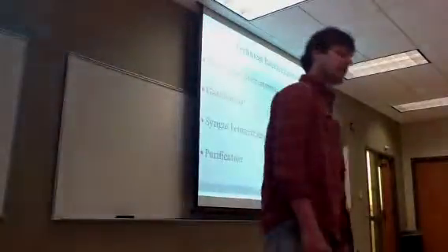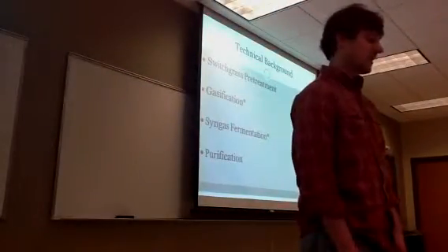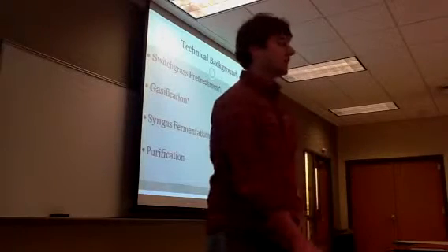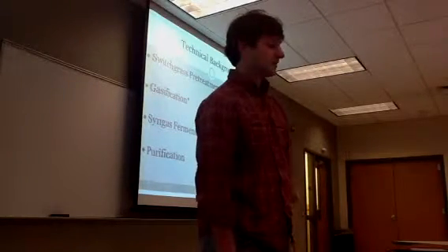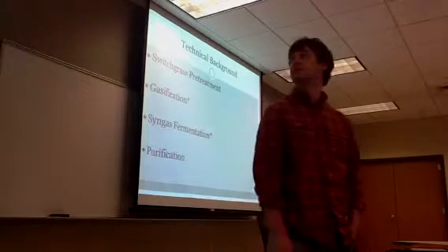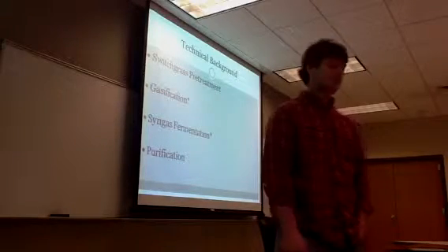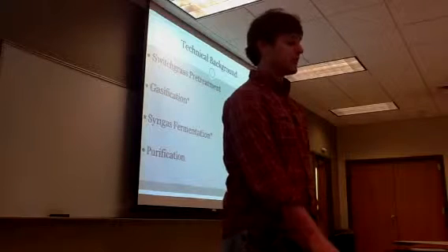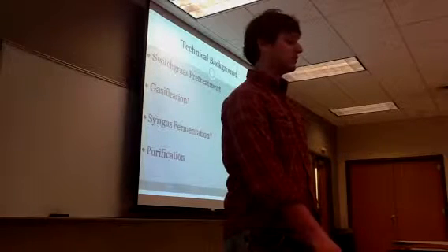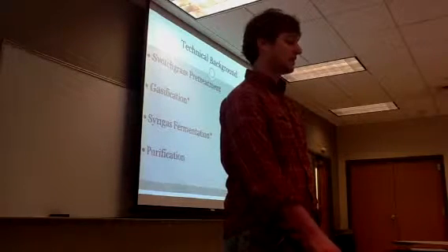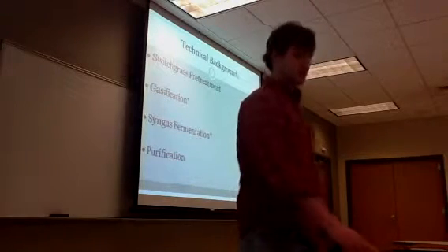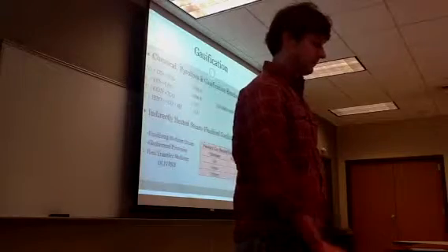I'm going to go over some of the technical aspects of our design. As Josh mentioned, first we're going to have a pre-treatment section, just to build up the switchgrass biomass component to a workable gasification feed stream. Next is gasification, which produces syngas, which will then be syngas fermented in a biocatalyst reactor, and then the purification stage to purify our ethanol.